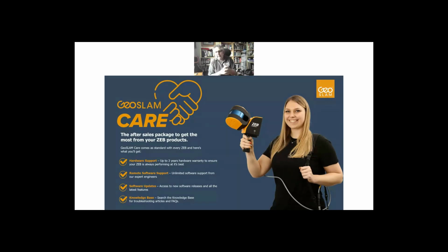So yeah, we talked about recommended walking speeds. I'd say I generally walk 1 to 1.5 meters per second. It is slower than I would generally do for a standard horizon. I want the best imagery, so I'm removing blur, even if maybe not through walking speed, but just by stopping any sudden movements of the camera, any twists. That's probably just as important as walking speed.